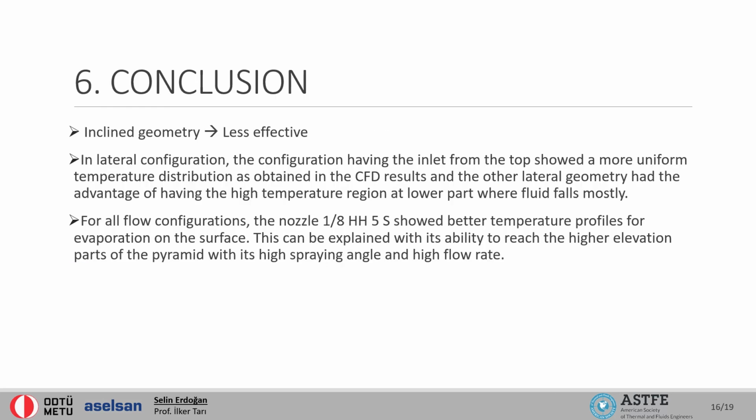To sum things up, the inclined channel geometry is observed to be less effective than the lateral channel geometry in both CFD and experimental results. In the lateral configuration, the configuration having the inlet from the bottom showed better performance as it had the advantage of having the high temperature region at the lower part where fluid falls mostly. And the nozzle having a larger spraying angle showed better performance as the evaporation surface is higher and a greater amount of wastewater can be dried.